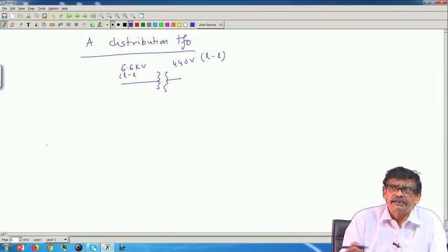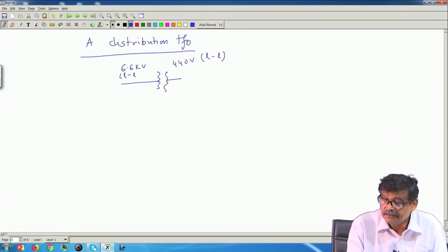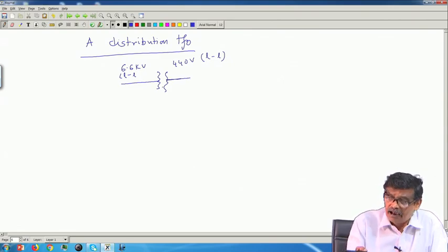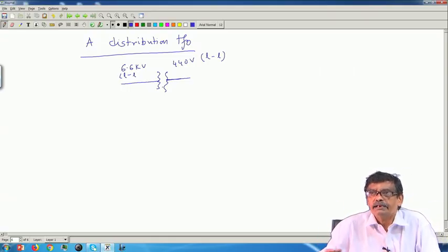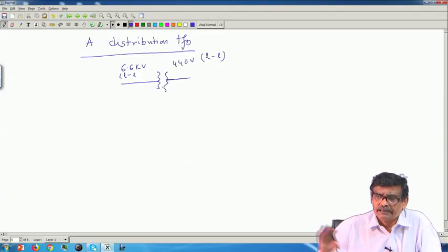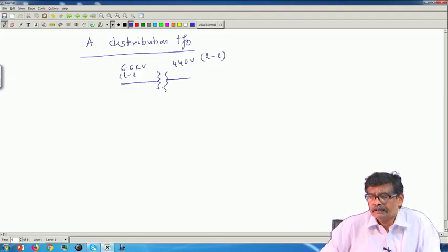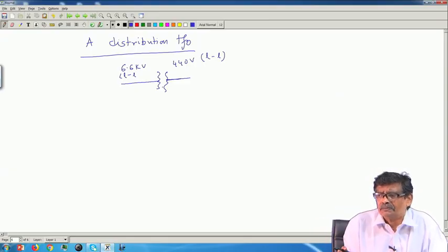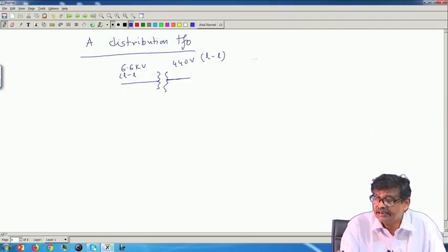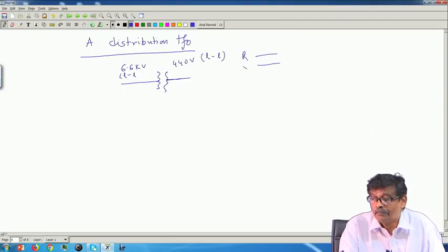We will discuss about the connection later, but let us try to understand. Now, the secondary of this, between R and neutral, a group of houses are supplied power. From Y phase and neutral, another group of houses or residential buildings are supplied, offices are supplied, B and N another. So, that is another job, that is to see that loads are almost balanced. So, here three terminals come, 4 terminals come out from this side, actually it is a single line diagram, just to emphasize this point.